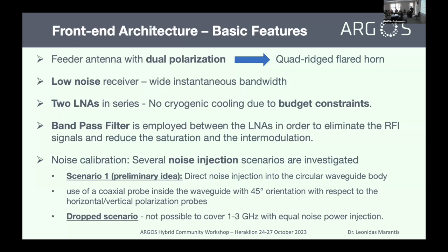The board that the Max Planck Institute is going to build is going to have two LNAs in series. We are not going to use cryogenic cooling due to battery constraints. And there's also a bandpass filter between these two LNAs in order to eliminate the RFI frequencies, these signals, and reduce the saturation and the modulation in our system.